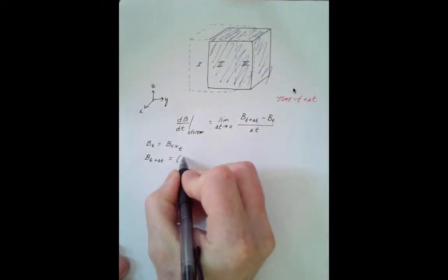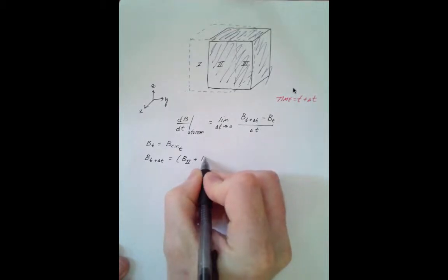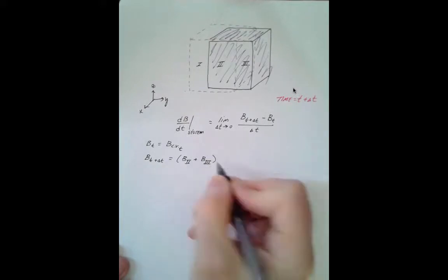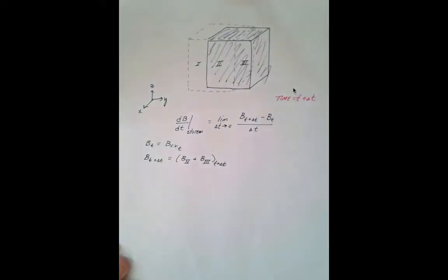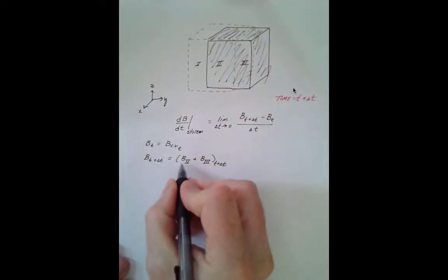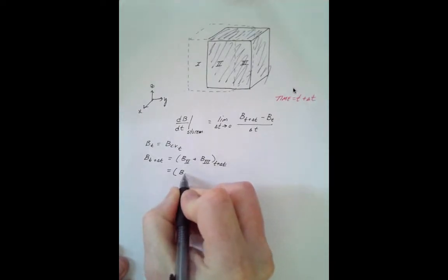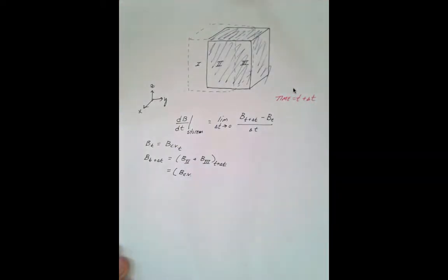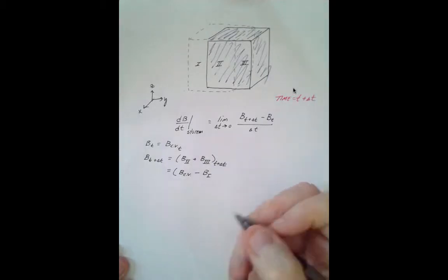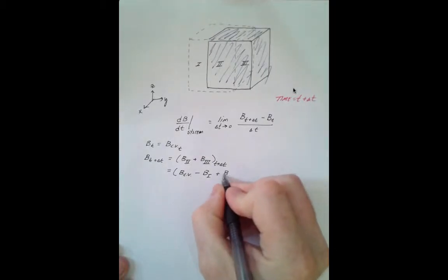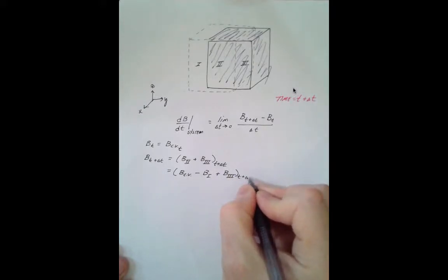It is including the amount of B in zone 2 plus the amount of B in zone 3, and that's at time level t plus delta t. The total amount of B hasn't changed. We can write B2 plus B3 as equal to the amount that's in the control volume right now minus whatever amount used to be in zone 1 plus the amount that's now emerged in zone 3, all at t plus delta t.